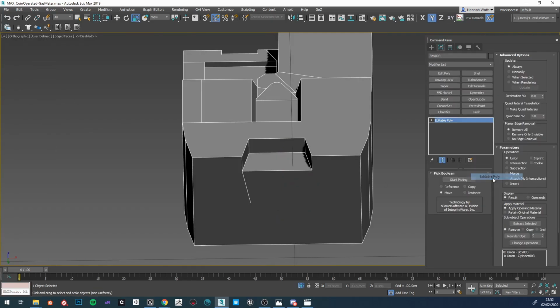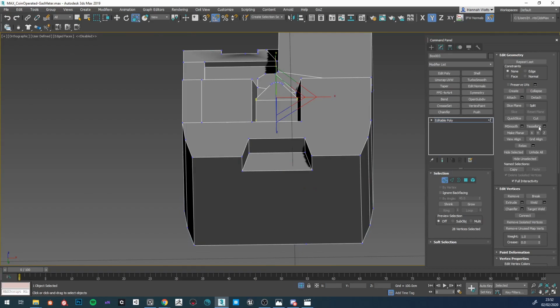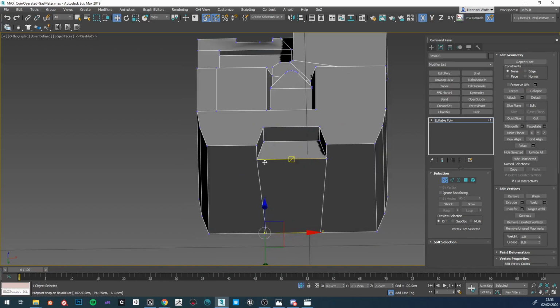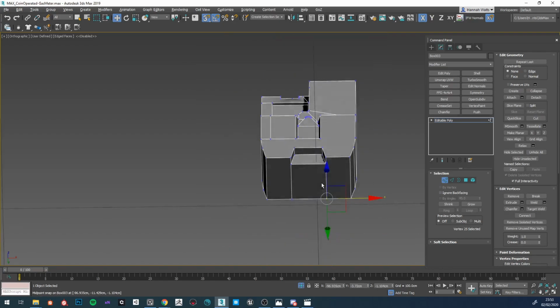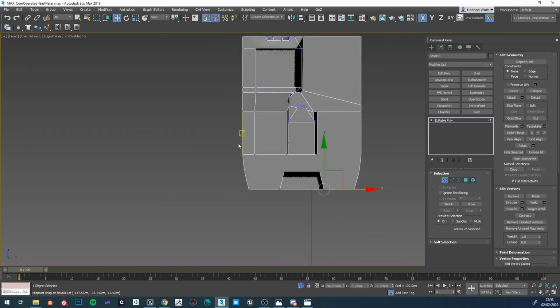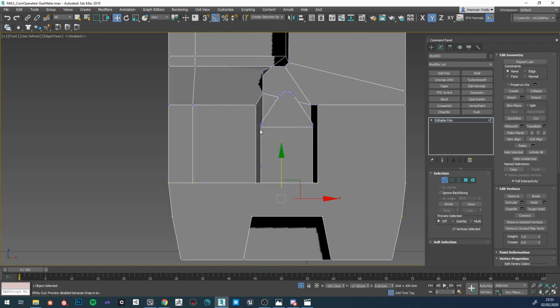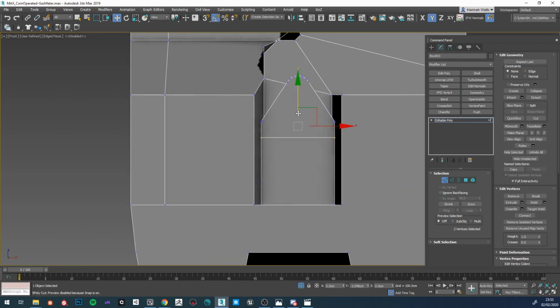Although I've said a few times that I'm not concerned with topology, I do need to clean this bottom bit up, as I've noticed that the two extruded capsule bits also extend down on the bottom as well. And so I need to get that in or I'll risk my design being wrong. I'm just using the cut tool and snaps here to fix the edge flow.